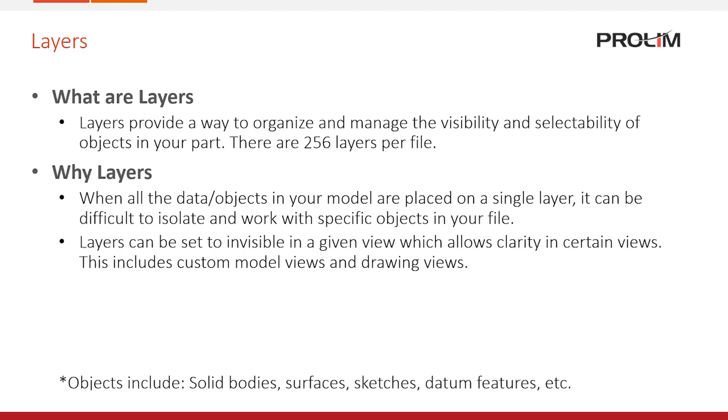It also allows you to set certain layers to visible only so that you can't even select them. So say, for instance, you had some bodies in there that you aren't going to be using for anything, but you want them visible in the background of the model. You can have those set to visible only, on a visible only layer, so that they can't be selected, which helps with selecting different models.